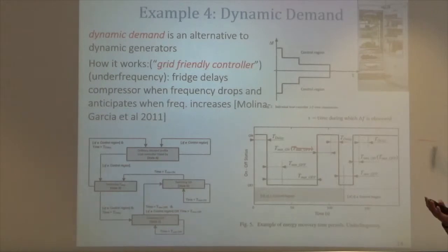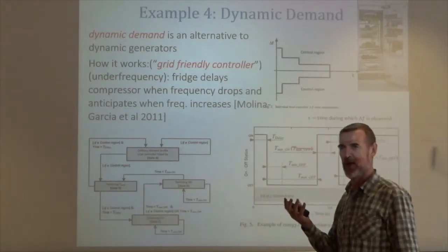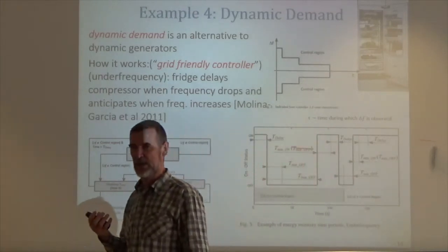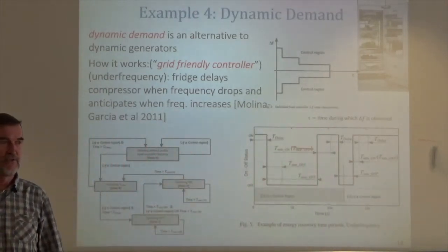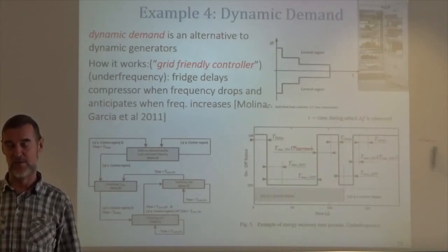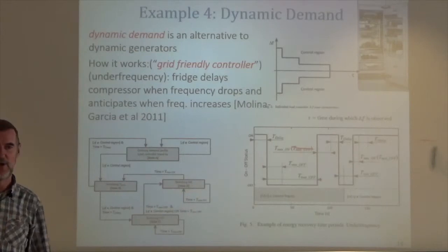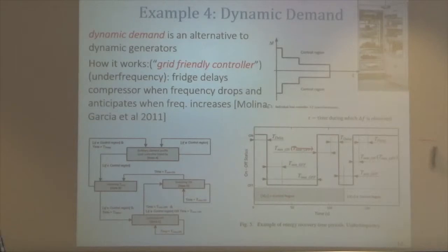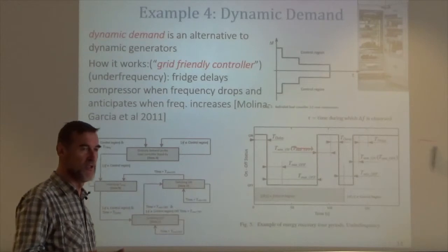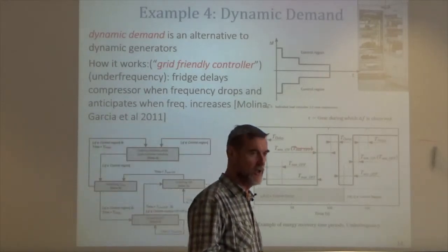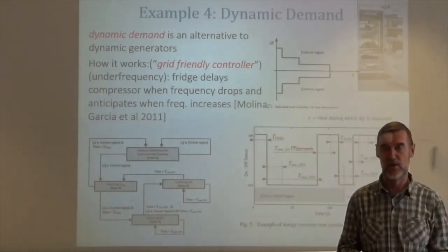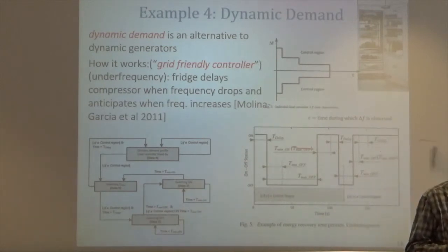Why is the problem coming more in the UK than in the rest of the world? This is because the UK is an interconnection of its own. Britain, so England, Wales and Scotland, is one synchronous system. Ireland is also another synchronous system. So those are synchronous systems that are much smaller than the rest of Europe, so the needs for regulation are much larger. They pay more for regulation. They are interconnected to the continent, but with DC lines, not with AC lines. So they are not synchronized with the continent.